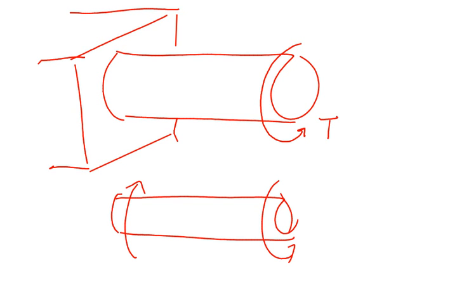The reason for that, of course, right, is equilibrium. In the top case, this is a fixed support on the left. The whole shaft must be in equilibrium. So if I apply a torque on that right-hand side, that support is actually exerting an equal and opposite torque. Okay, so these two cases are actually equivalent. Right? These are static equilibrium cases. And most of mechanics of materials does deal with static equilibrium.